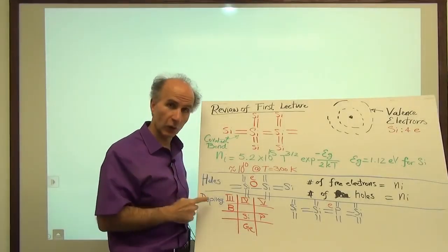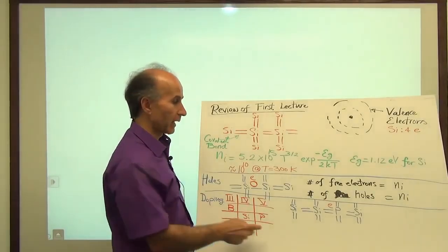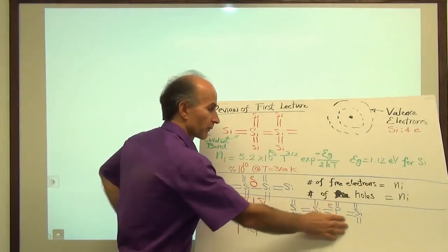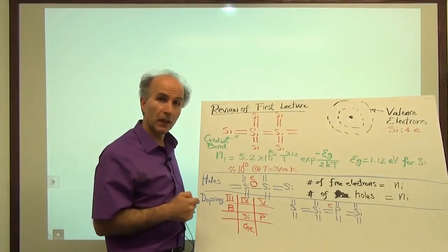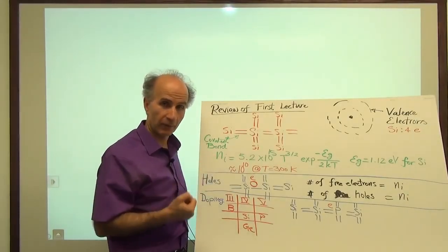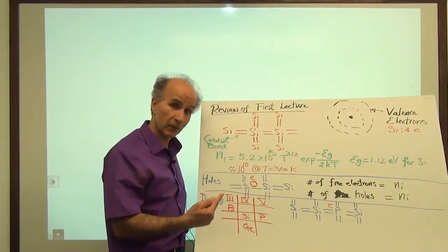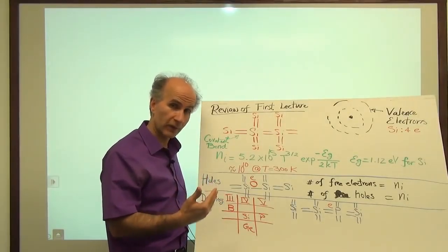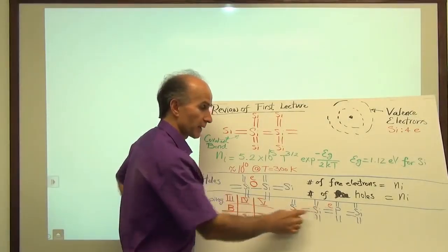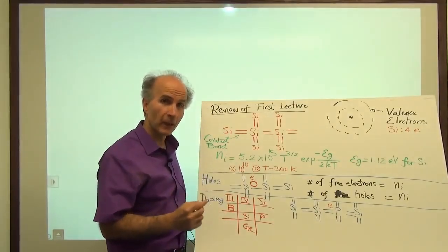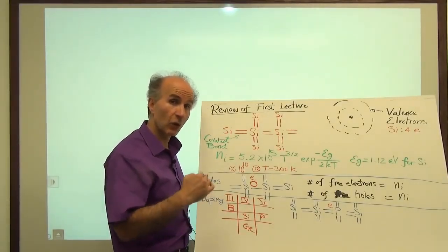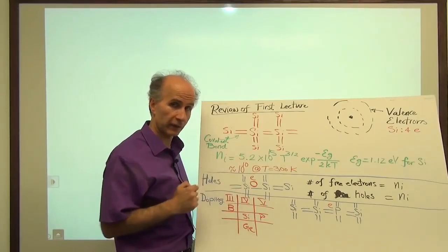And that's what we call doping. So we can increase the number of free electrons in the material by doping, for example, phosphorus. If we do that, we call this an N-type material because now it has more electrons. Also, the phosphorus itself is called the dopant or a donor because it donates electrons for current conduction.